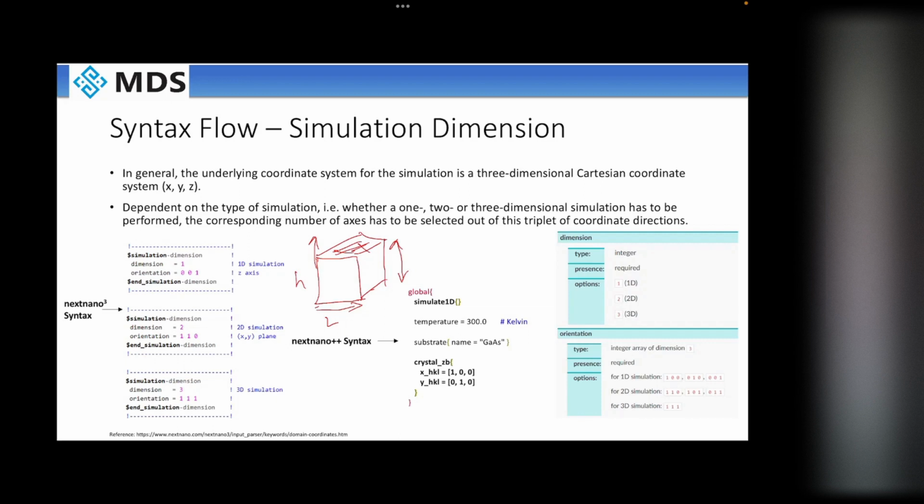Instead, to see how the doping will look, you can simply take a 2D view of it, placing a contact on the top, or you can take a 1D by making a cut line here, and it will be like this. Here, these two parts will be my contact, and it will show the doping concentration.